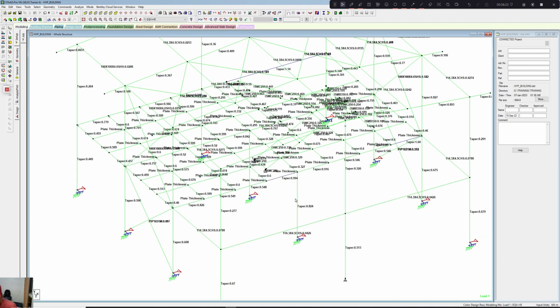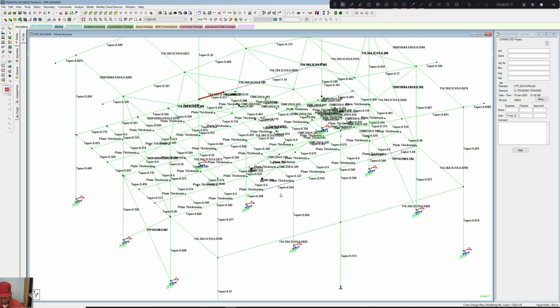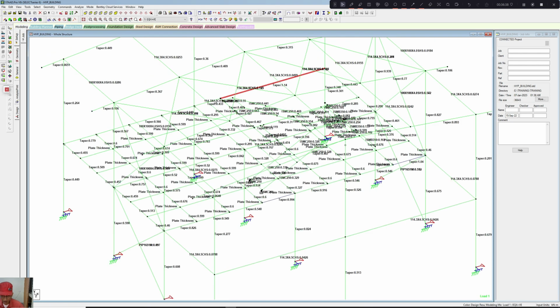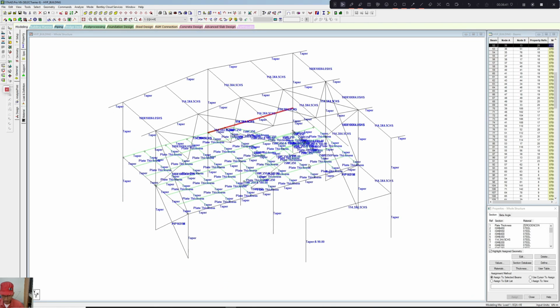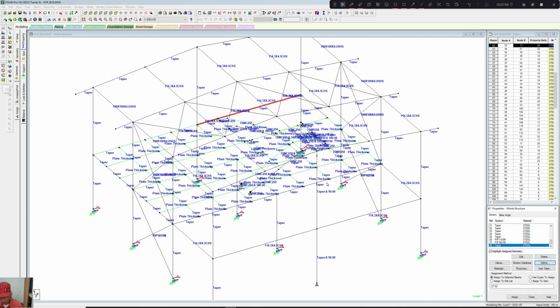This is now okay, but our two beams are now actually failing. If you see the blue color, they are critical. So we'll change these sections. Let us see what is the section, 370 by 175. So let us make a section 370. General, define, taper I, 374, 0.005, 374, 0.175, 0.012. Assign.